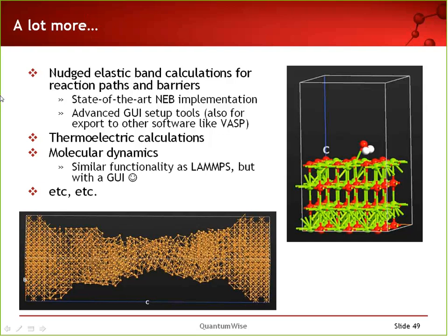There's another question that reads, can ATK model non-self-consistent tight binding models? Yes, we have a set of built-in tight binding models. Some of those are self-consistent, some of them are non-self-consistent. It's also possible to include your own tight binding model, again, self-consistent or non-self-consistent. So if you have in the literature a particular model, it can be DFTB, it can be Slater-Koster tight binding, non-orthogonal. Then you can actually insert those parameters into the software and run all the transport or band structure, whatever calculations with. So just taking your parameters and running them with our engine. That's possible.